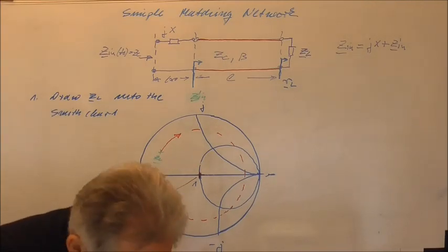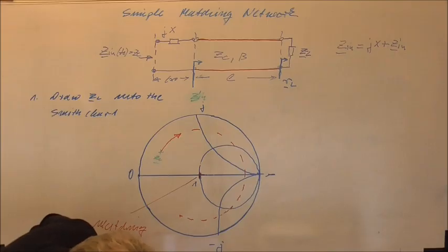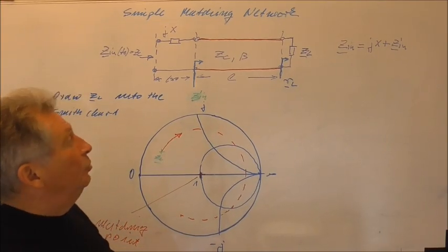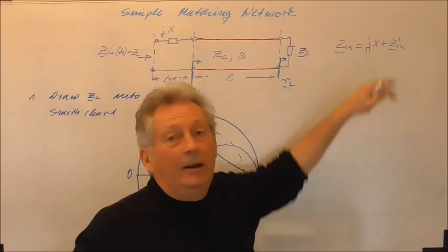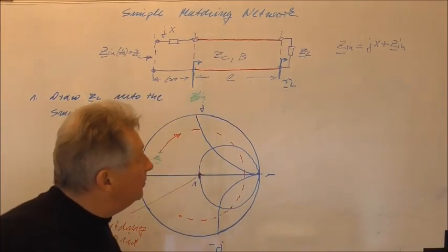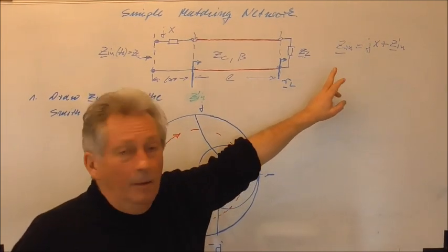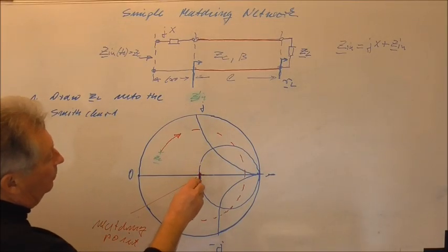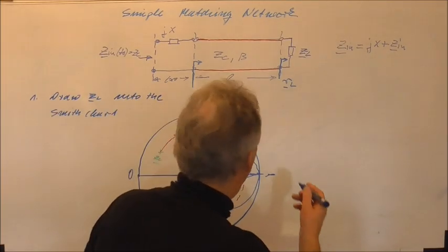So, you mean what kind of reactance should we add to make it move to the origin, right? Yeah, we have two possibilities. You have the possibility to use a positive reactance. This means you use an inductance, or you must use a capacitor, then you use a negative reactance. But as a result, I want to be here.